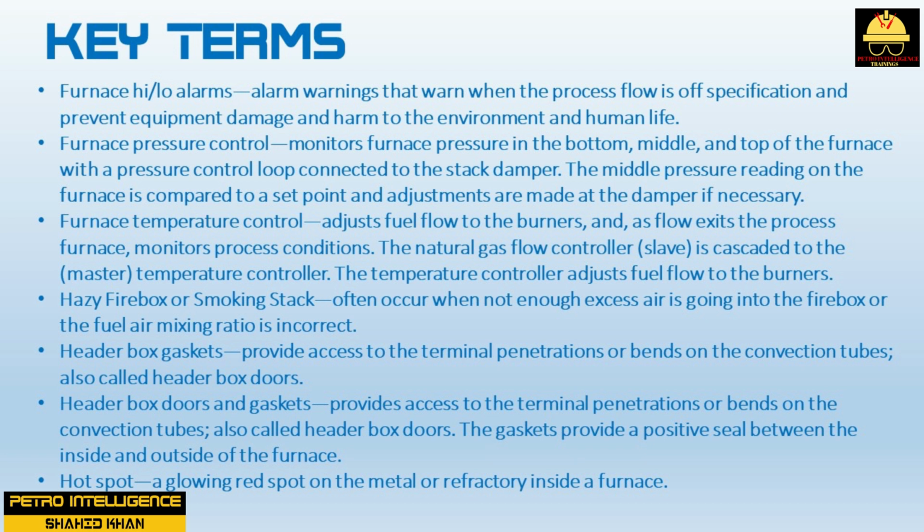Furnace pressure control monitors furnace pressure in the bottom, middle, and top of the furnace with a pressure control loop connected to the stack damper. The middle pressure reading on the furnace is compared to a set point and adjustments are made at the damper if necessary.